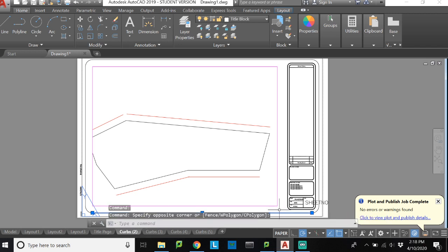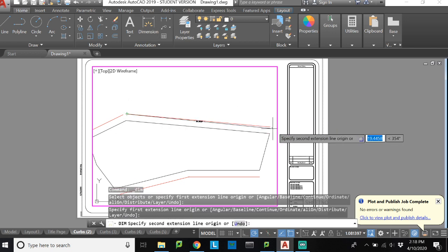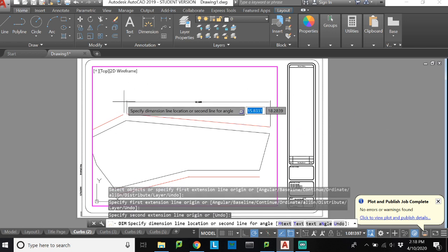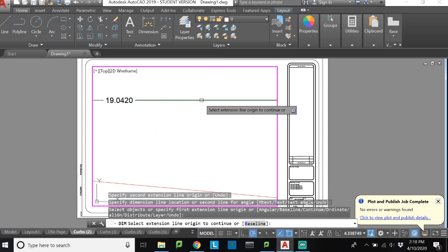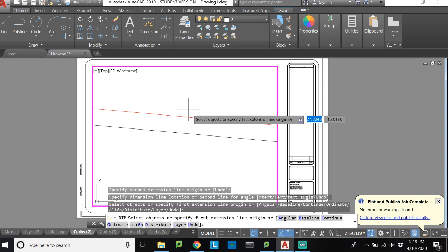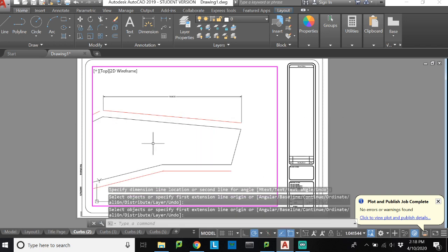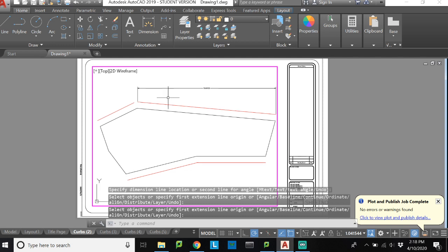Now, another suggestion that I do have is when you go to make dimensions on this drawing. If I go into my model space and I make dimensions in here, that's fine and great, dandy. Those dimensions are pretty and everything, but they will look a little bit small because this is a 24 by 36 inch page.